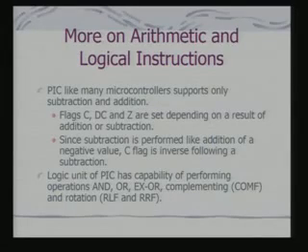Now let's look at more information. Let's look at and understand more information about arithmetic and logical instructions. PIC doesn't support complex arithmetic operations. It supports simple addition and subtraction. Because PIC in its basic form is not really targeted for, say, signal processing applications or number crunching applications. It is typically targeted for simple control or instrumentation applications. In that case, addition and subtraction operations actually can meet majority of requirements.